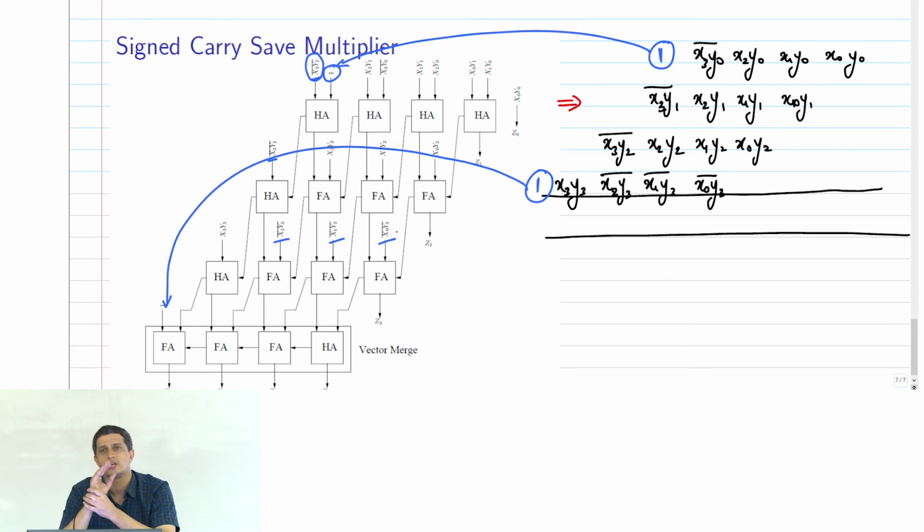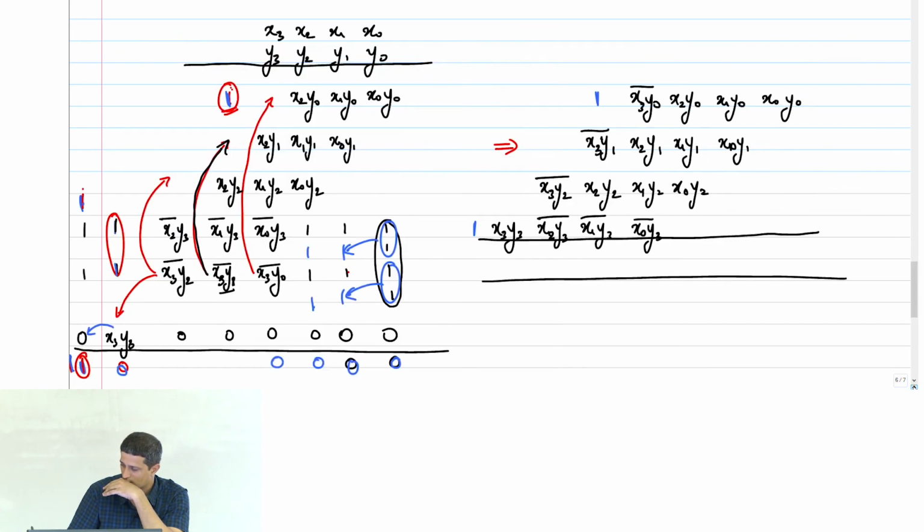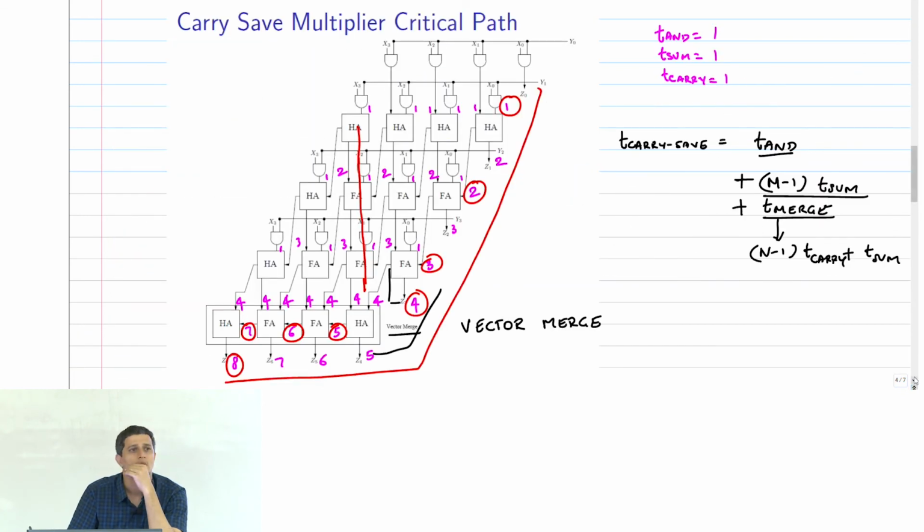Final thing I'm going to leave as an optimization for you in the project. All through we have done AND gates. But of course, since this is in the critical part, it's better I do NAND gates. If I make everything NAND, then I need to change this. It has to become a half adder prime in the sense where it takes complements and gives out complements. So when you design your multiplier, please make sure you optimize for this NAND gate as opposed to trying to use an AND gate.